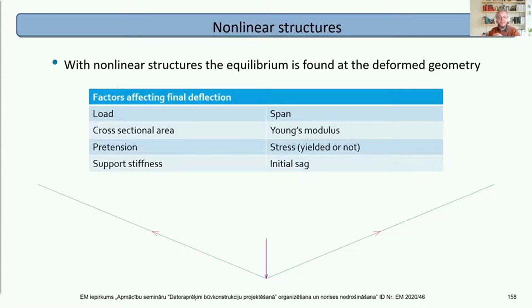Now, on the other hand, if you start out and say, I want the deflection to be this much, then if you define the deflection first, it's very easy to work out what all the stresses and strains and so on are on the structure. So it becomes quite a linear analysis if you start from a defined deflection. But then you go work out what size of structure, length of cable, and so on you need to generate that in the first place. There are ways and means.